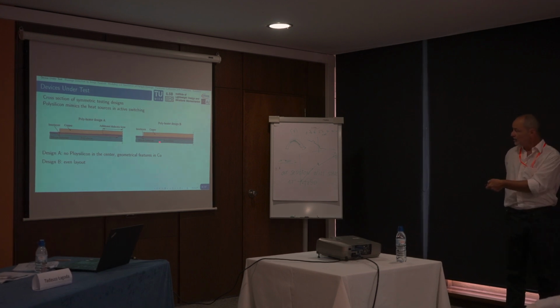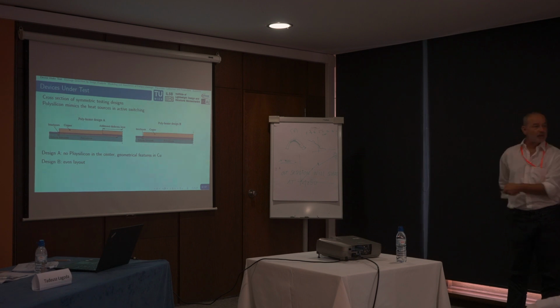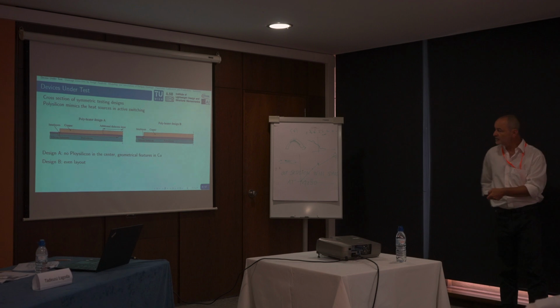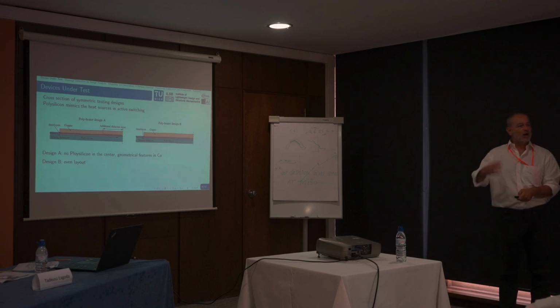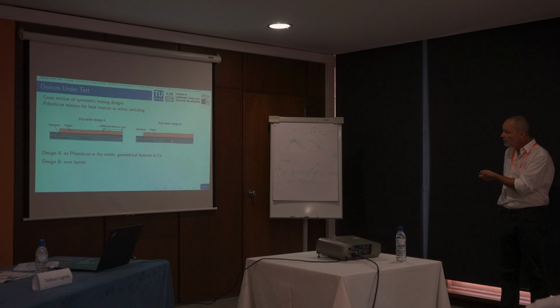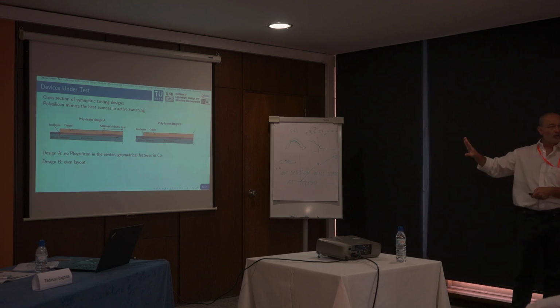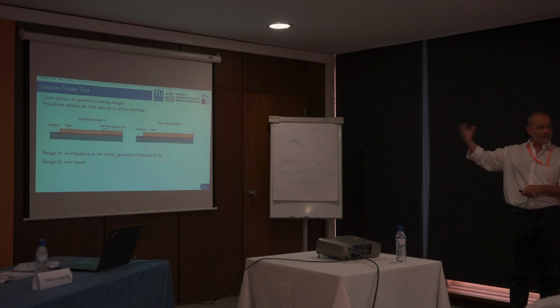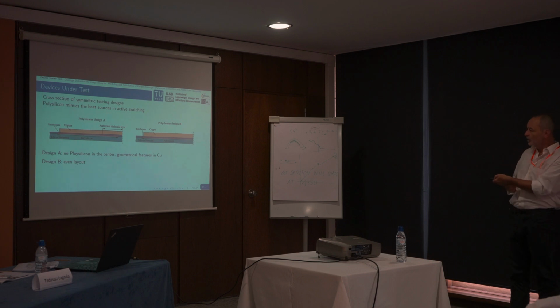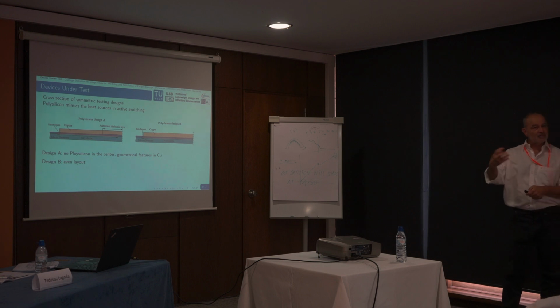You see silicon, the gray part, which is much thicker than shown here. And close on top there is a copper layer. The copper layer is about 30 micrometers, and the silicon is about 200 micrometers or more. But close to the interface, there is this red area called polysilicon, and this mimics the power generation. Infineon can produce this on purpose, and it has the same features thermomechanically as a real chip, but it's much cheaper. The red line here is the power dissipation, the heat sources.